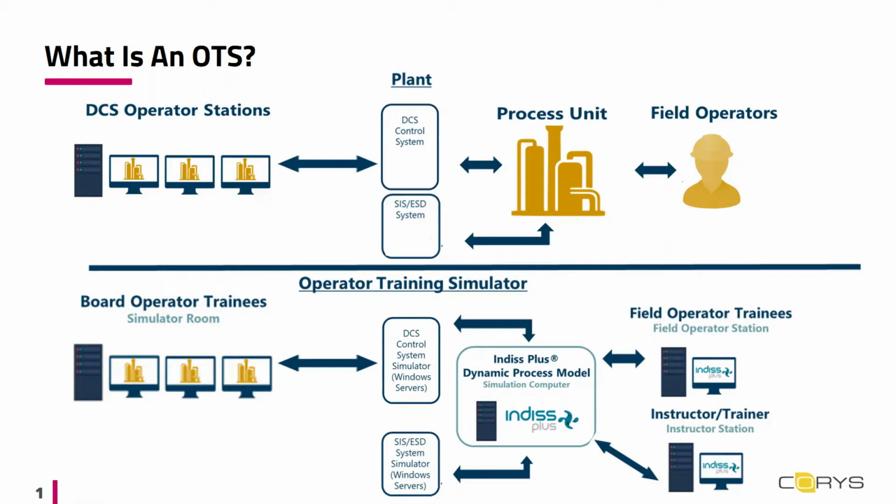The DCS is simulated by a DCS simulator, and the SIS is similarly simulated by an SIS simulator. And then you have your DCS operator trainee stations. The only component that doesn't have an equivalent in the plant is the instructor station. And this is where the instructor will run the simulation, introduce malfunctions, activate training scenarios, and more.